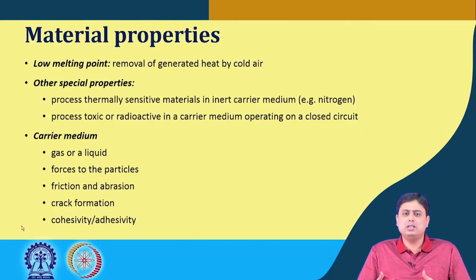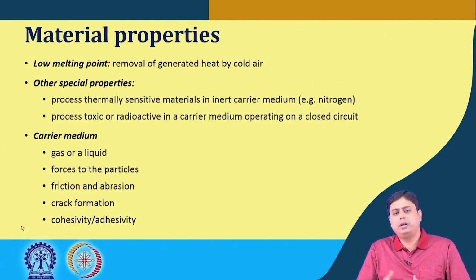It totally changes the hydrodynamics of the flow. Moreover, we must consider the influence of carrier media on crack formation: whether it makes the solids more brittle or tougher. Depending on that scenario, we have to choose the size reducing equipment.